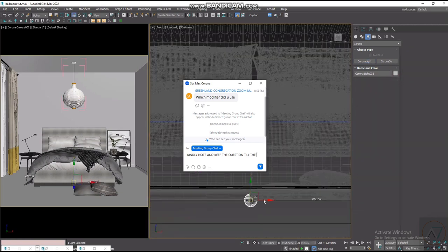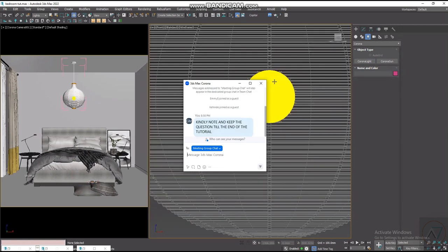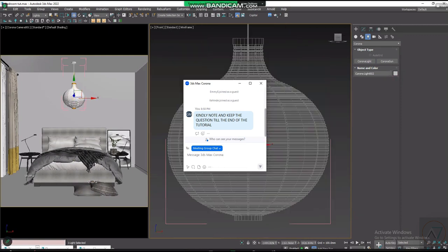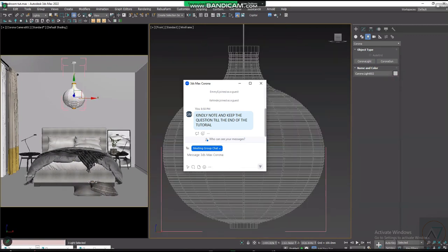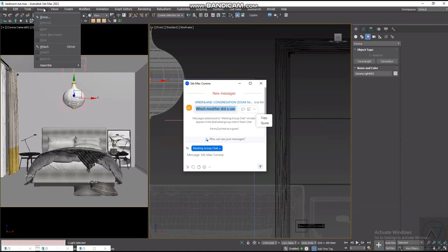So change to W to move. Now, if you remember, we copied the height of our light here earlier. So just paste it, Ctrl V. You can see our light is now at the same spot. We deleted the gray light. So yeah, I'm okay with this light. Then now I'm going to attach this light to this group, the group of this pendant or whatever it is. Click on the light, come to this group. So we are clicking on the light only, come to the group.